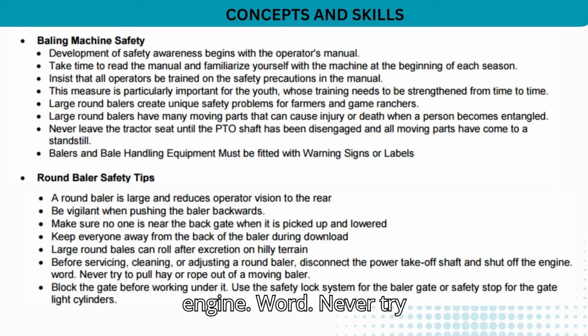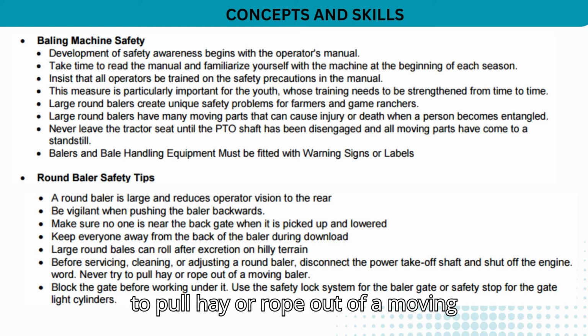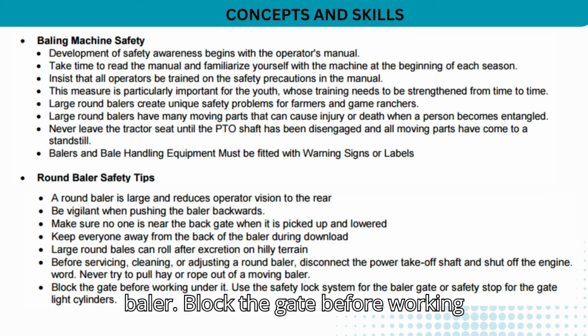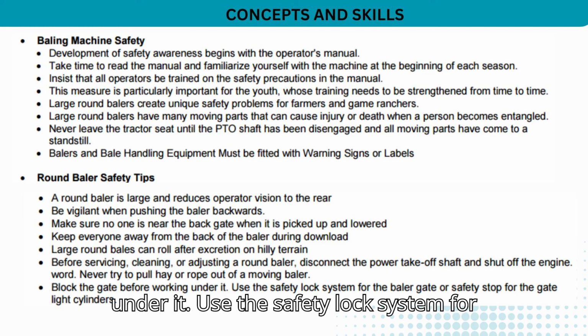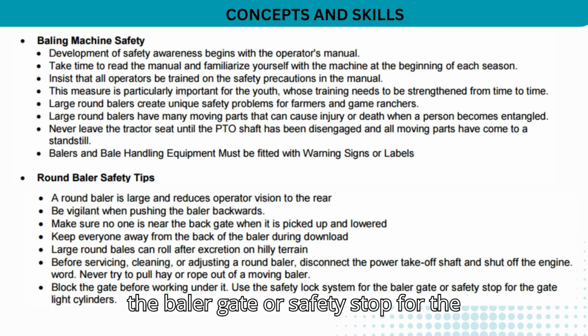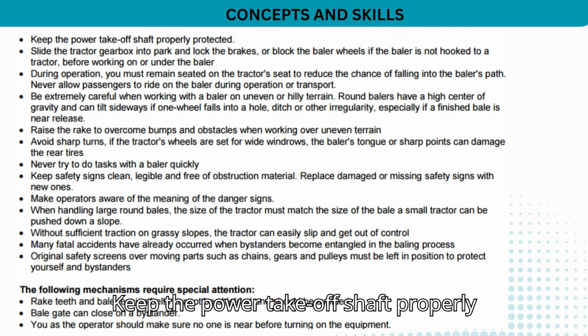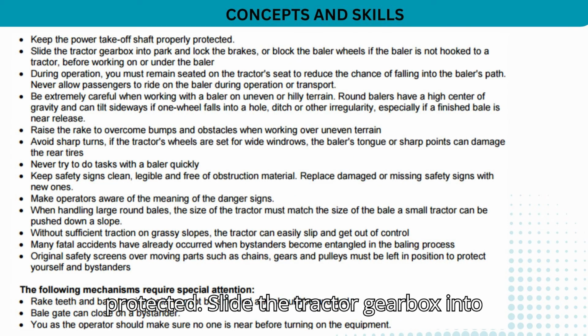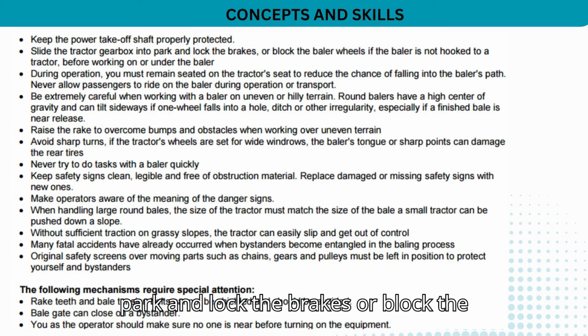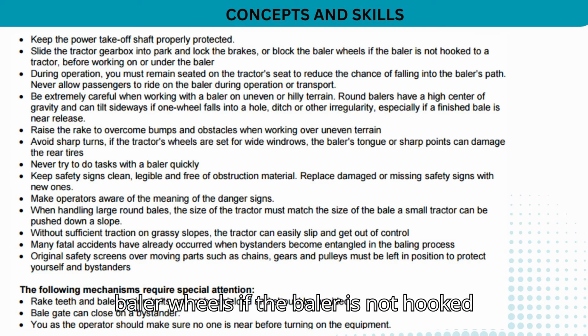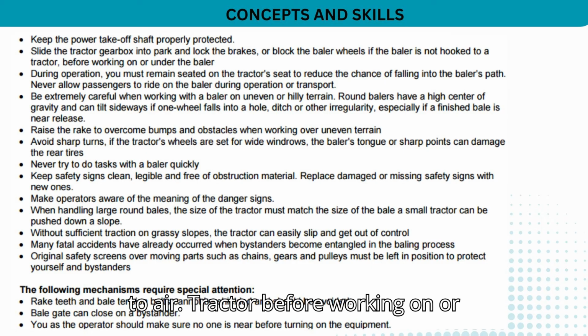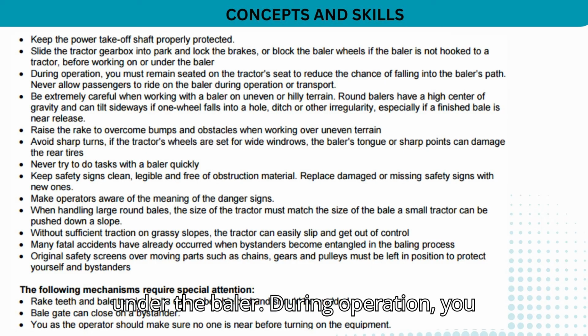Never try to pull hay or rope out of a moving baler. Block the gate before working under it. Use the safety lock system for the baler gate or safety stop for the gate cylinders. Keep the power takeoff shaft properly protected. Slide the tractor gearbox into park and lock the brakes, or block the baler wheels if the baler is not hooked to a tractor, before working on or under the baler.